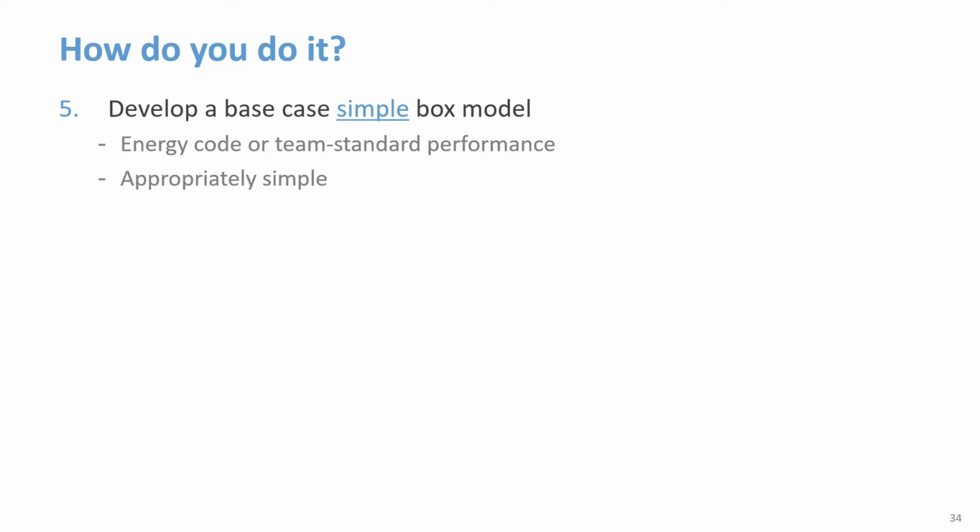So now we can get to start creating a base case model. The starting point, or the base case, is often a model with code minimum inputs for things like envelope performance and lighting power and HVAC efficiency, but the design team may have other preferences for a starting point, maybe based on a previous design or the firm's typical standard. It doesn't really matter, but typically you choose one starting point.